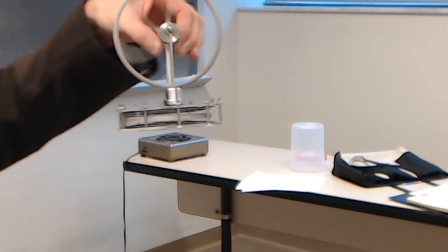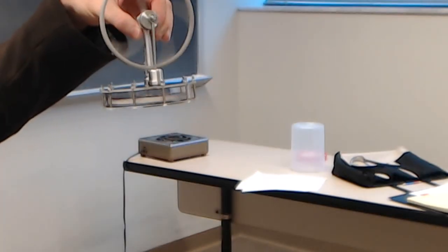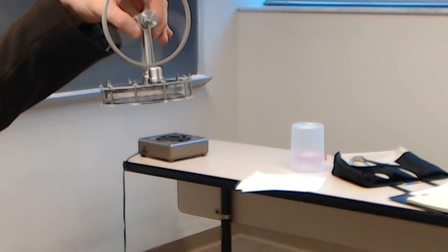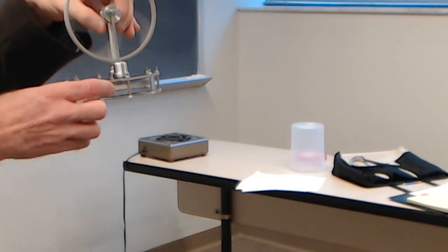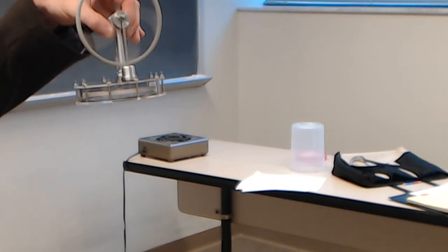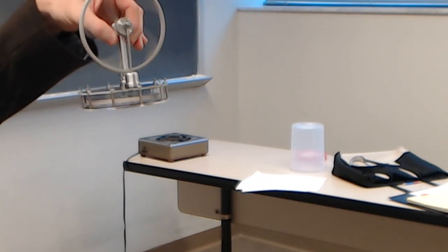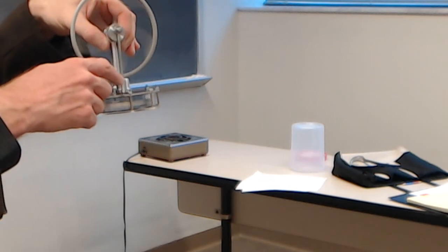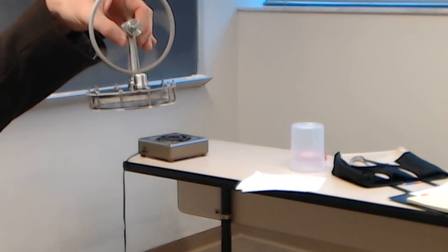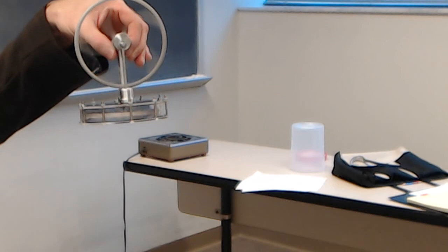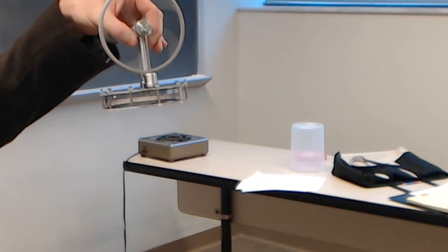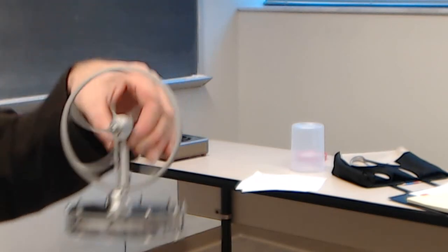There are hobbyists who make terrific brass models of these things with literal candle power for them, and 4 or 6 pistons and such, all working off a common crankshaft. And because the pressure inside is very close to atmospheric pressure, it's not a high-pressure engine, which is the whole idea of the Stirling engine. They're very safe to work with, and they don't require extremely fine machining. You've actually got a little bit of slot between the piston and the cylinder here. It's not exactly airtight. Some people have made Stirling engines using plastic syringes and test tubes and a set of marbles. I'll have to link to some videos on those.